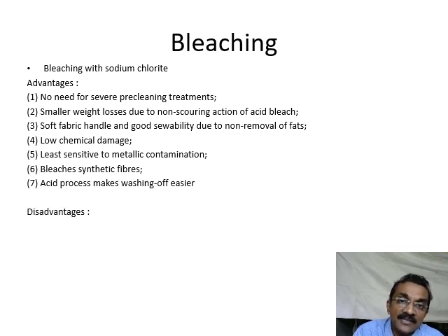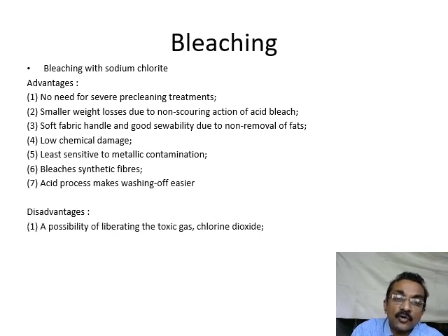There are a few disadvantages to this process, in that there is a possibility of liberating a toxic gas, chlorine dioxide. During the reaction, chlorine dioxide is a harmful gas mainly responsible for suffocation. So this process is generally carried out in very closed vessels. Very specific equipment is required. Even at the time of operation, if there are some leakages from the machines, those are very toxic. So major precautions are required.